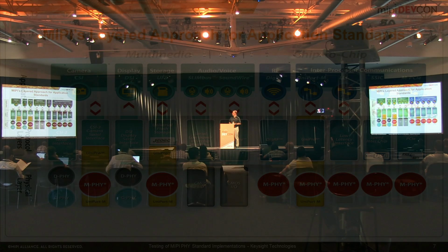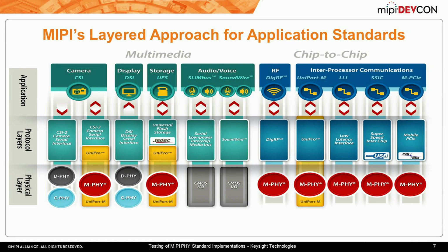Okay, let's take a quick look at the MIPI interfaces here. So let's see if I can try this laser pointer here. So there's really three primary high-speed interfaces. We have D-PHY and C-PHY is right there, okay? And then M-PHY, you'll notice in the red bullets over here and these ones here. These are the high-speed interfaces that are the more challenging ones to validate in MIPI. MIPI also has some much lower speed interfaces. We're not going to be talking about those today.